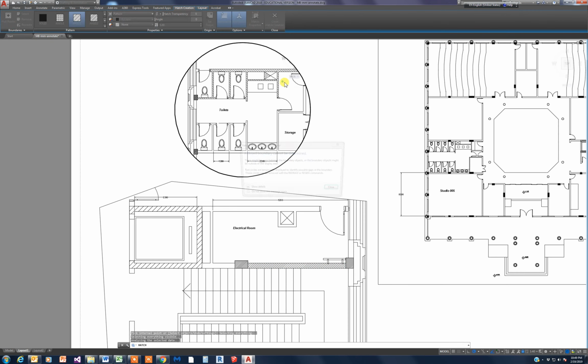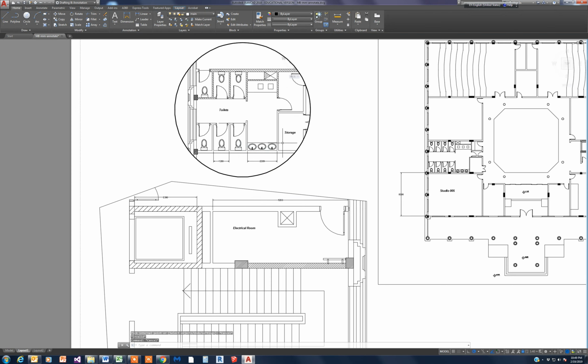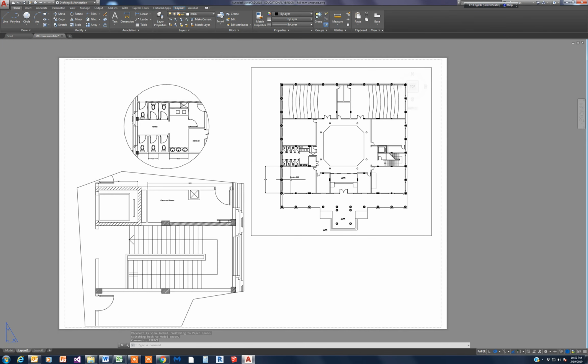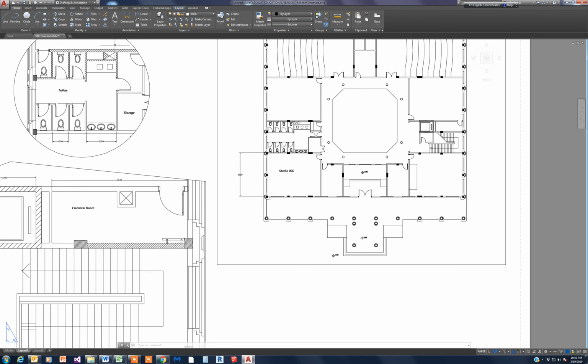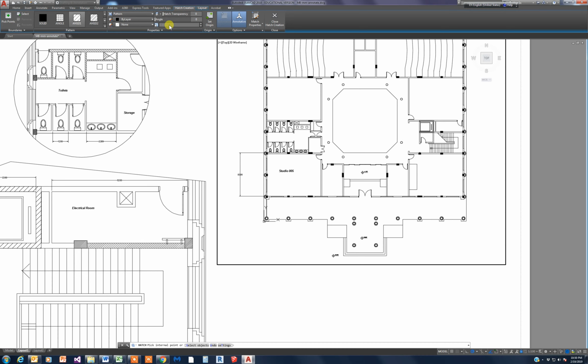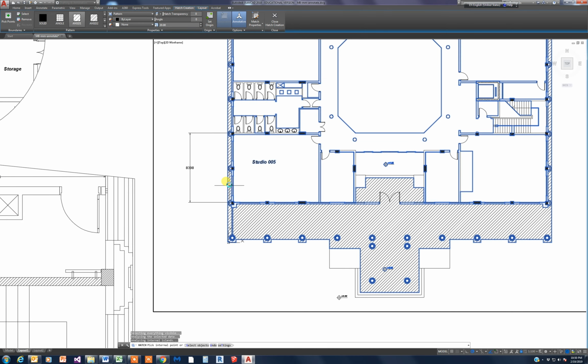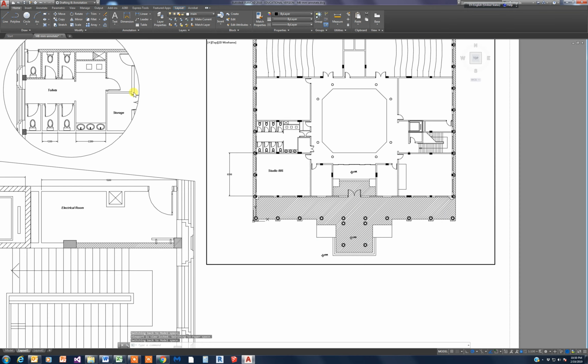So if I go back here, okay, I have to escape, I'm inside, I select, it's 20, this is 20, so you could see the same hatching, and this is what you want. You want to unify the hatching. You don't want the hatching to be affected by the size of the drawing or the scale. So again, if I'm inside here, I'll go hatching, make sure it's Annotative. It has to be 20, and I will try to do this. Okay, it's demonstration. So now you see, even at 1 to 100 scale, it's still the same.